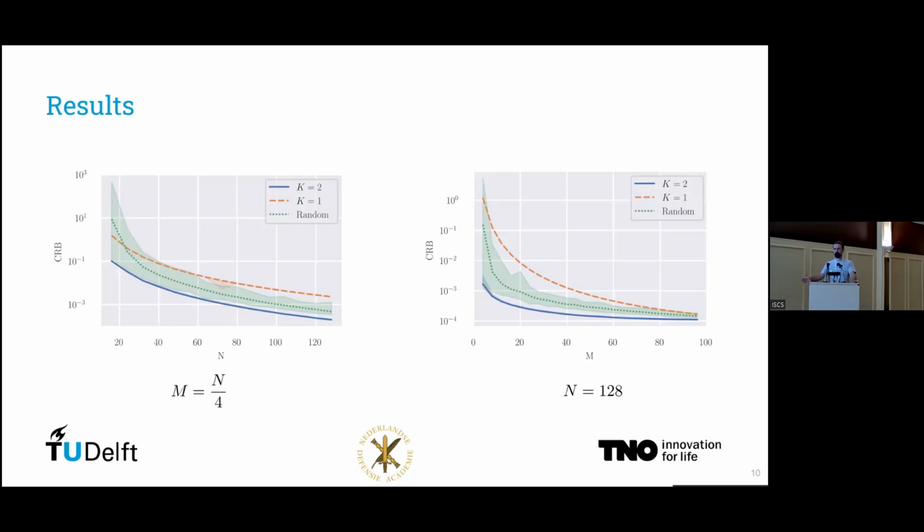The other one is that we assumed that the target reflected signals were uncorrelated and of equal power. We want to see what happens if there is correlation between the targets. It will make the optimization quite a bit more challenging, but for certain applications of radar, you just cannot assume that they're completely uncorrelated.